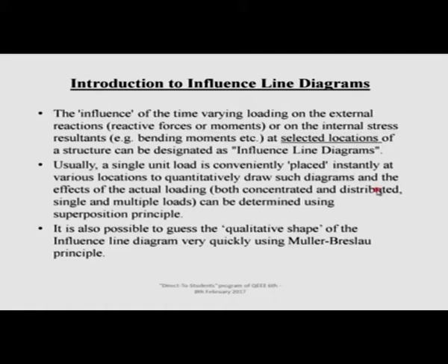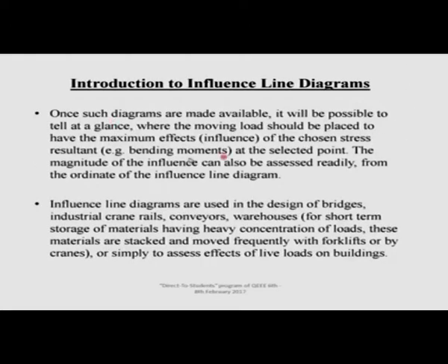It is also possible to guess the qualitative shape of the influence line diagram. We will discuss using a principle called the Muller-Breslau principle, which is a very, very powerful tool in structural analysis. You will see that. Once such diagrams are made available, it will be possible to tell at a glance where the moving load should be placed to have the maximum effects, influence.